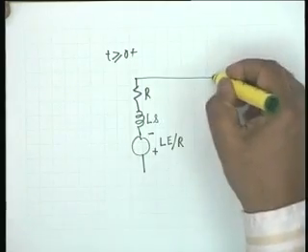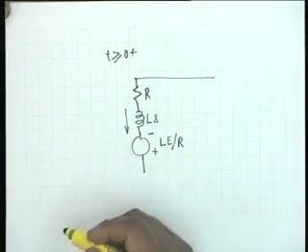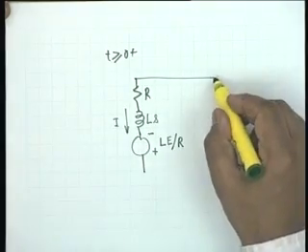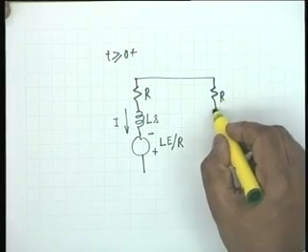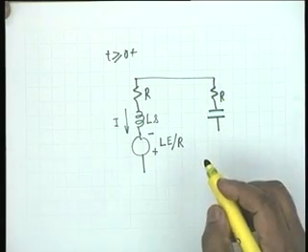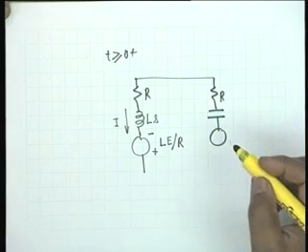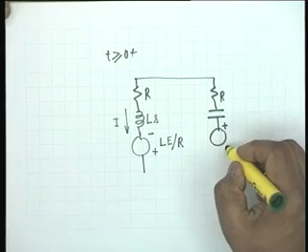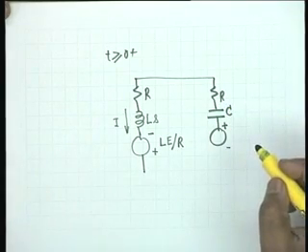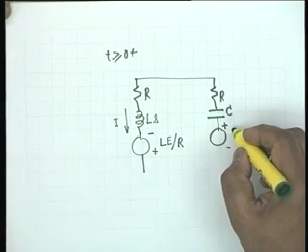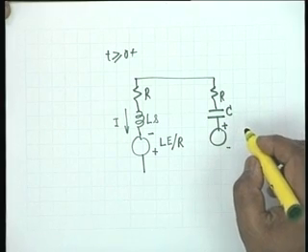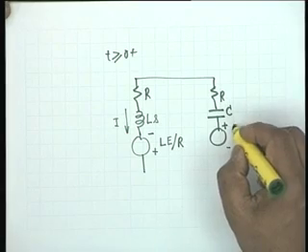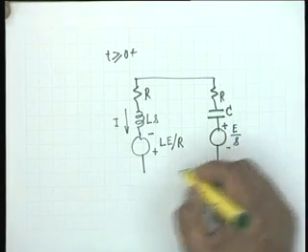The current transform is capital I. For the capacitor, you have R, then an uncharged capacitor C in series with a voltage with this polarity, whose value is Vc of 0 minus divided by S because you are taking the transform, and therefore this will be E by S.